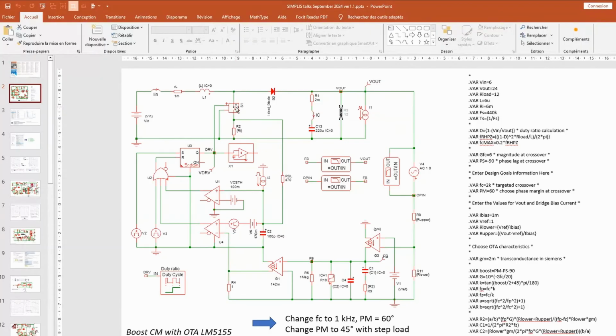Also, something that I favor, and we'll show that in a moment, is these blocks here. I like to automate things. It means I'm trying to explore different compensation strategies, and by compensation strategies, I mean poles and zeros, which are there to neutralize the variability of the usual offenders. These offenders being, of course, the load resistance, the ESR of the capacitors, all the parasitics that are going to move during the production process or the converter operating lifetime.